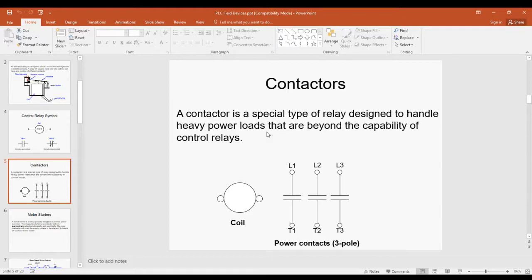We're able to step AC voltages up real high, which lowers the current. And by sending AC power out at a high voltage, low current, it turns out it's much, much more efficient to transmit energy that way. So that's why we have AC and DC. We have AC to transmit the power for the most part. And when we get the power where we need it, often we change that AC to DC. So you might plug your cell phone or your computer into the wall, thinking that you're plugging it into AC, which you are, but that device has circuitry in it to change the AC from the wall back into DC.